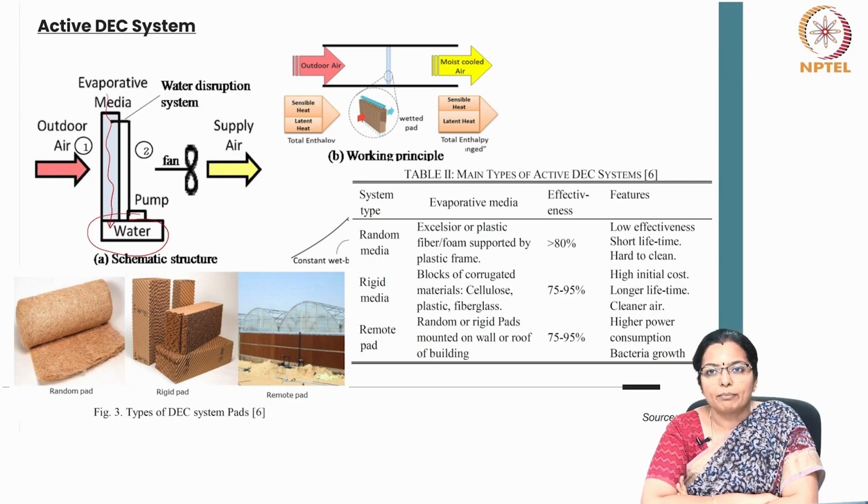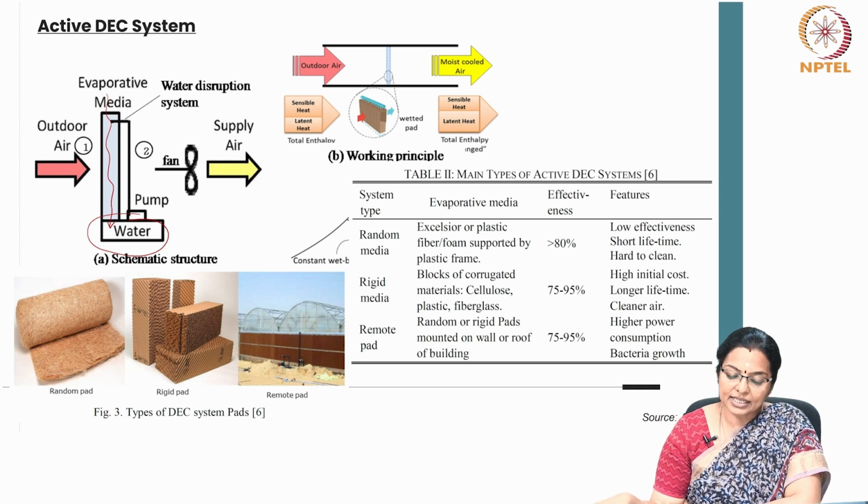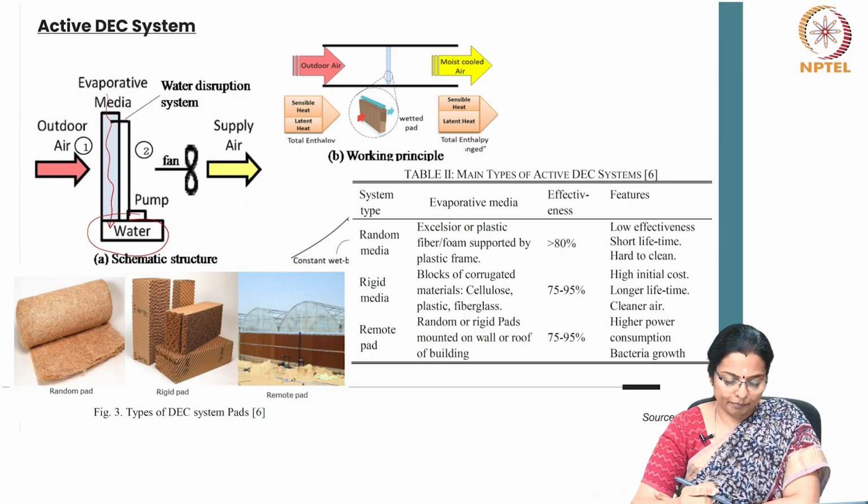The direct evaporative cooling is an adiabatic cooling process, which means that the total enthalpy of the air remains constant throughout the operation. Water absorbs the sensible heat from the supply air and evaporates. This lowers the temperature and increases the humidity.